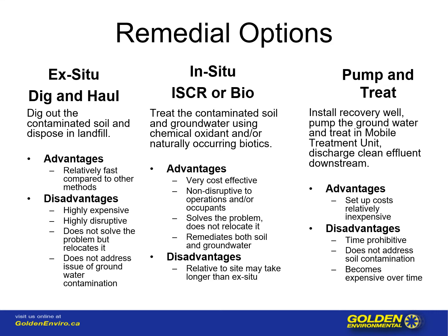Other things to consider when choosing an in-situ remediation option is infrastructure. There are some chemical oxidants that will corrode certain metals. There are some oxidants that may damage certain underground infrastructure, like telephone lines, certain cast piping, etc. So it is very important to understand the locates, what is happening in the subsurface, before one chooses to inoculate a site with the oxidant.